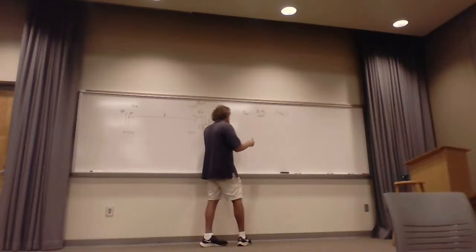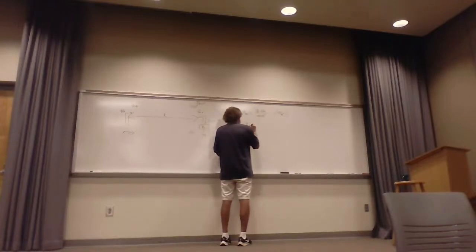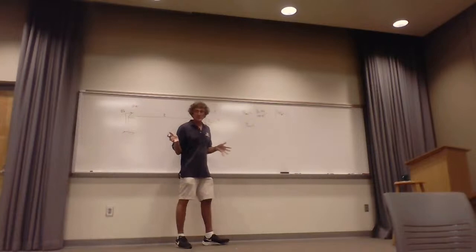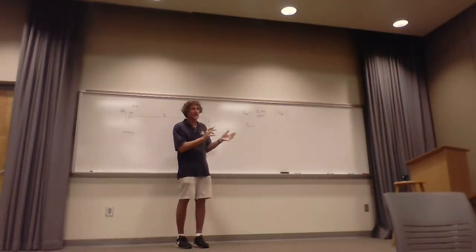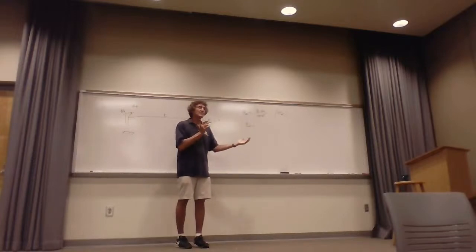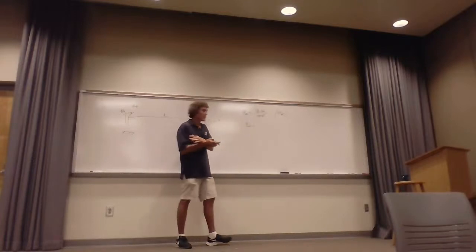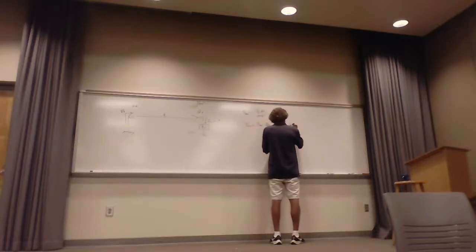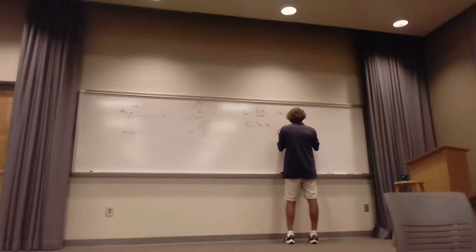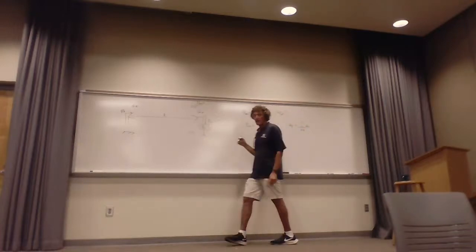Now to get the power received, and this is theoretical. It isn't actually the power received, is it? This is only a theoretical constraint. It's the maximum power received, and even if all of it's received, half of it is re-radiated anyway. So this P received is going to be P average times the aperture of the antenna. The aperture is the electrical size, lambda squared over 4 pi times the gain of the receiver. Y'all remember that?